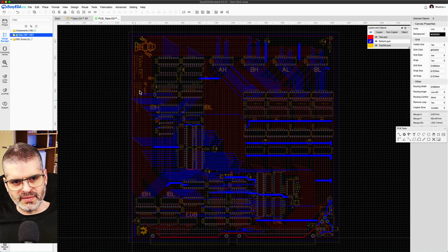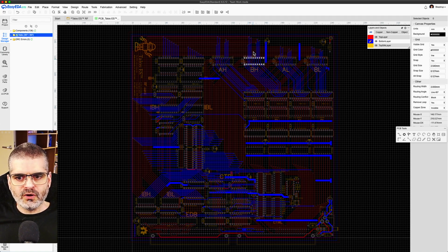I chose to, when I bent the local bus here, invert the rule. Consequently, on the top part of the board, red is horizontal and blue is vertical, even though in the rest of the board, it's the other way around. And I did it because I knew I could. I have a CAD tool that shows me all the rat lines, what needs to be connected with what, and you can play around with it, and you know that you can do it, and it will save you more impedance mismatches. So that's what I did.